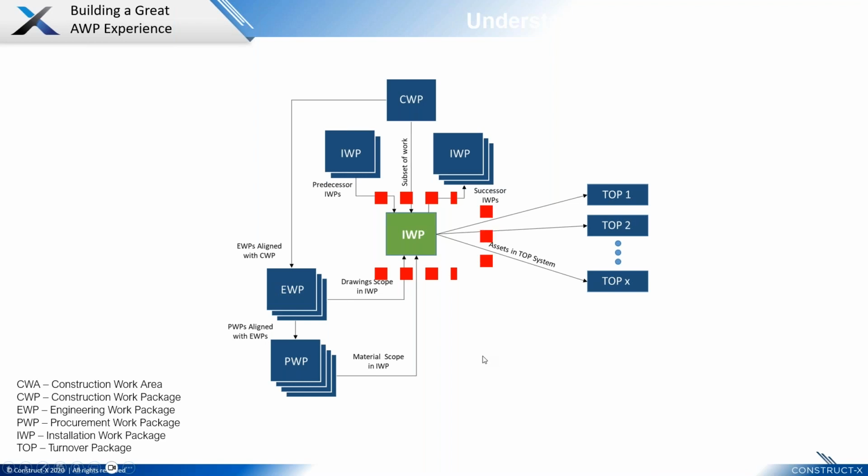And let's see, I think I have one more. Again, the same one. Trying to protect our turnovers, or at least letting the sequence of work of these IWPs help accelerate our turnover of the systems, basically the turnover packages, so we can have an efficient startup. So again, it's never letting bad work make it into the IWPs, or the IWPs not being completed or addressed make it to turnover packages, where all of a sudden we got massive punch lists. So we didn't follow these good guidelines.